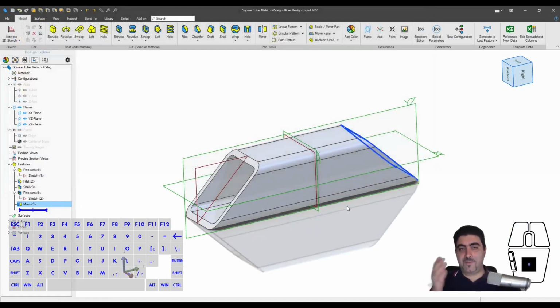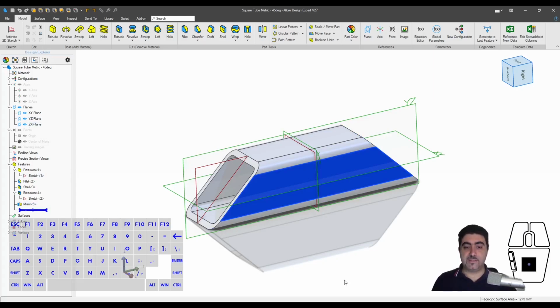Okay, so what have I made here? So this is another toolbox part. It's another square tube, but it's pre-cut, 45 degrees at both ends, symmetric cuts, right? So imagine now that I want a square welded frame from square tubes, or a rectangular welded frame from square tubes, and I want those tubes mitered. Well, for square or rectangular frames, the miter is going to be at 45 degrees. So look at this. There you go.